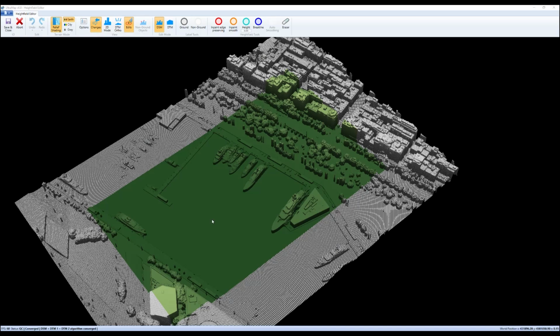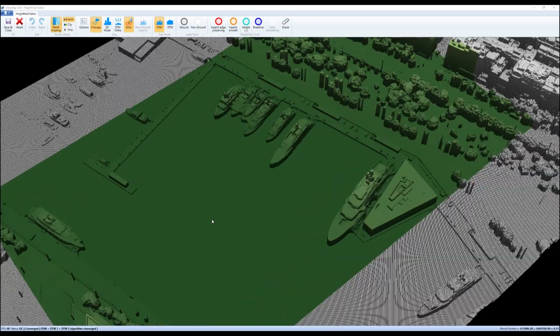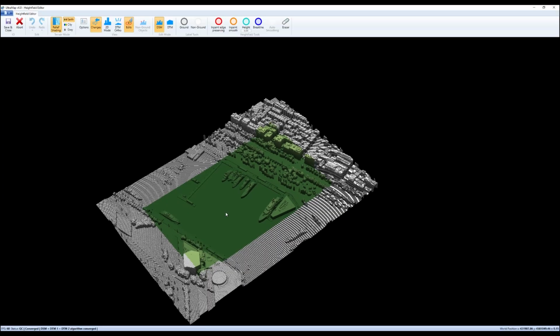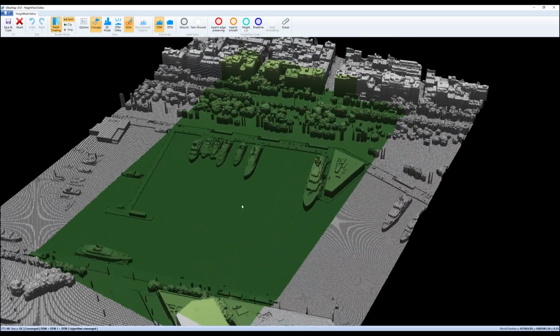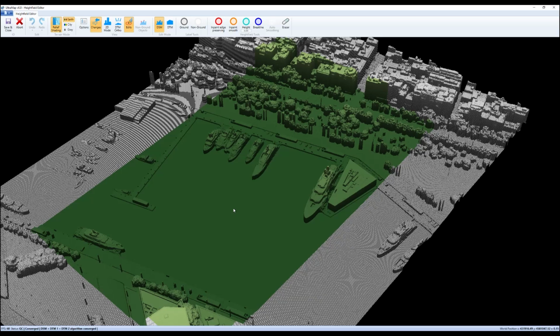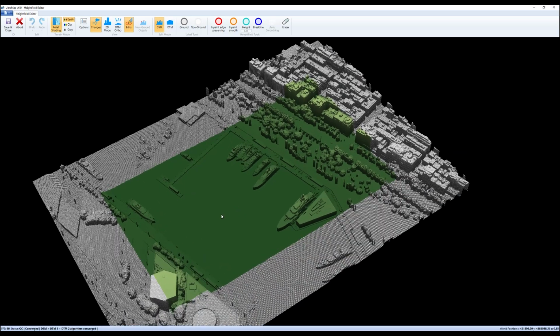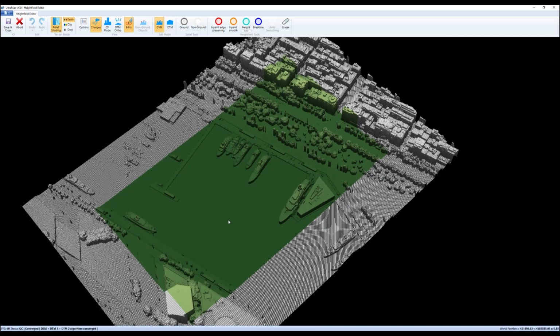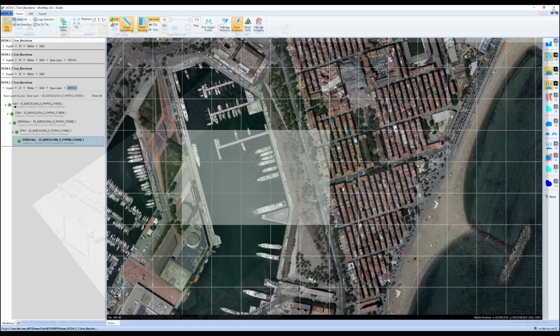In the height field editor, you can load the DSM and DTM at full resolution and interact with the data, so modify with any of these tools. So these tools have not changed in comparison to UltraMap version 5, just the speed with which you can open and interact with this editor. This has been changed for version 6.